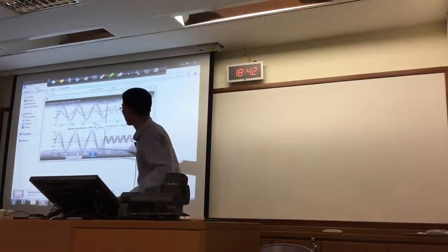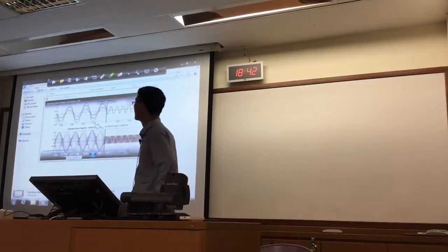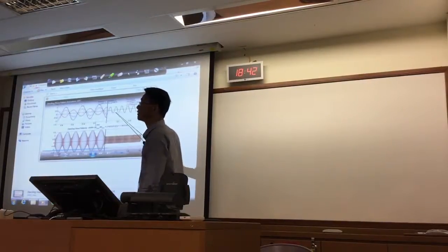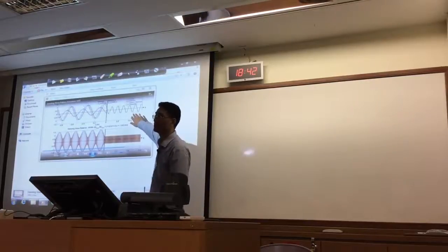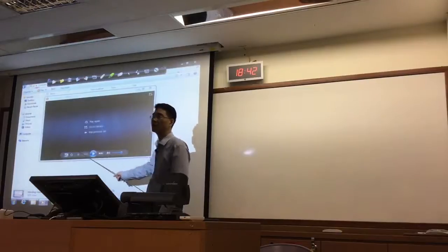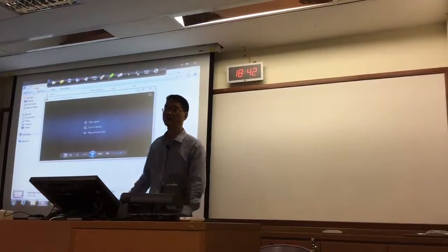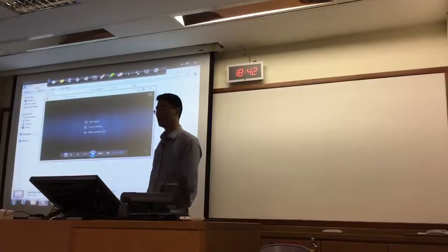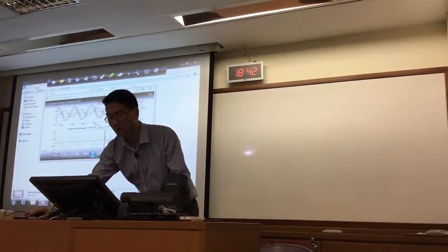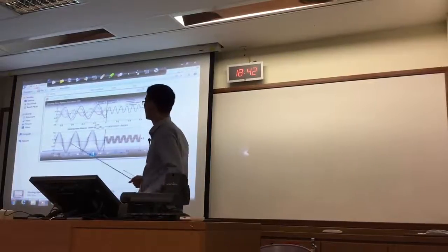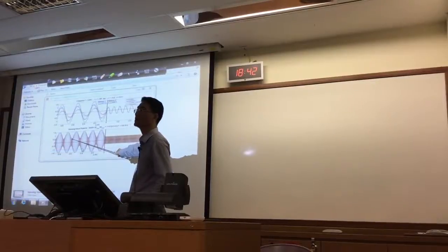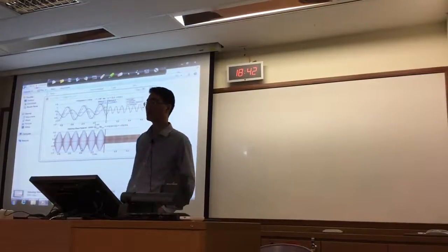Initially it is a traveling wave, then with the reflected wave it forms the standing wave. This is, for instance, the traveling wave with no reflection. Here is the boundary, where incident and reflected waves form the standing wave. So what is the SWR? The standing wave ratio is the ratio of this maximum to this minimum.